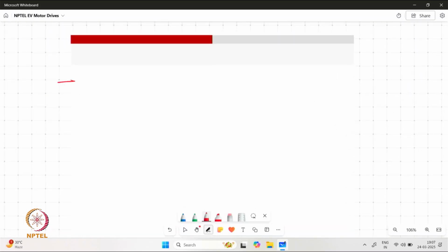We have the input voltage corresponding to the alpha axis available with us, Vs alpha, where we are subtracting the drop in the resistance, and eventually this generates Es alpha, which is integrated to generate our stator flux along the alpha axis.